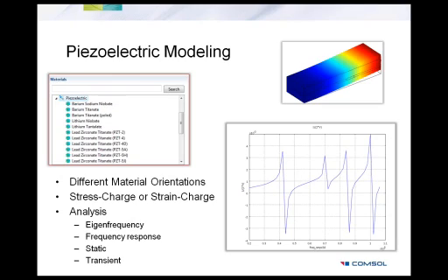And with piezoelectric materials, the other thing is basically the material cut angles, which are also very critical because they determine the wave propagation direction. And COMSOL makes it very, very easy to define your own coordinate system through an Euler angle representation. Most of these materials with different cut angles have their own Euler angle representation. So you can look it up in the literature and just type it in the user interface, and you can make those in the simulations. So it's as easy as that.